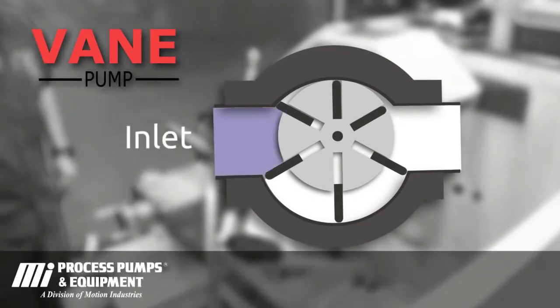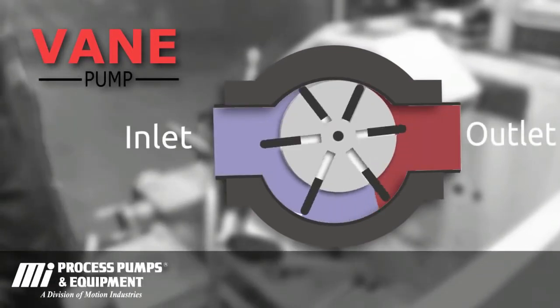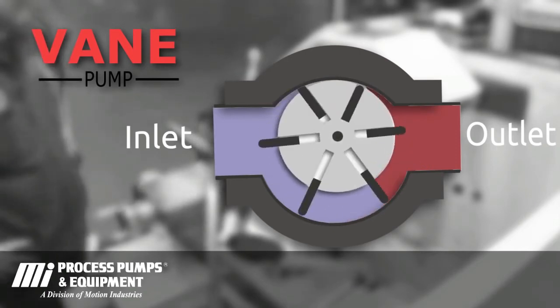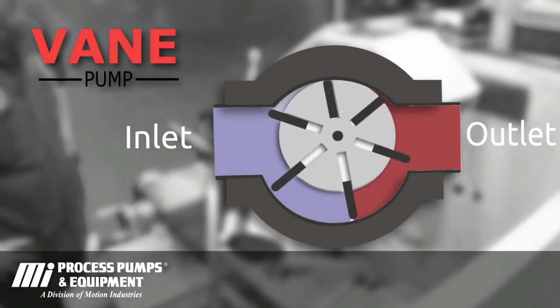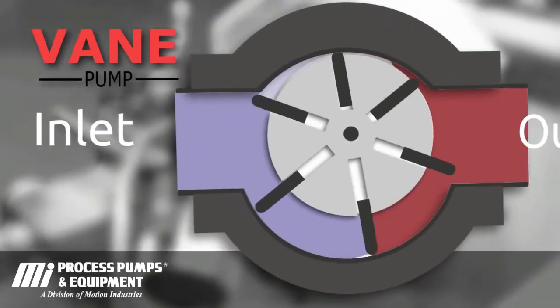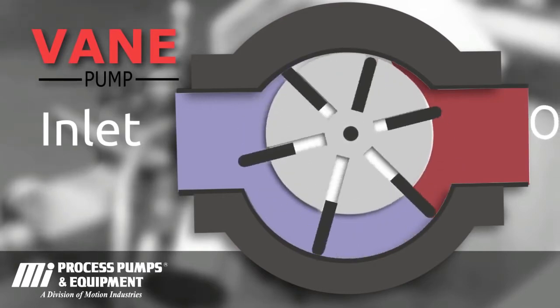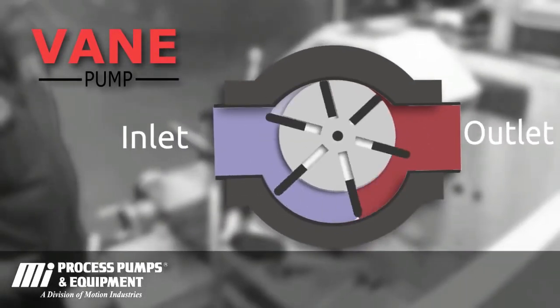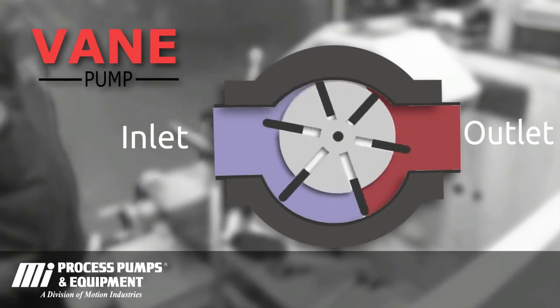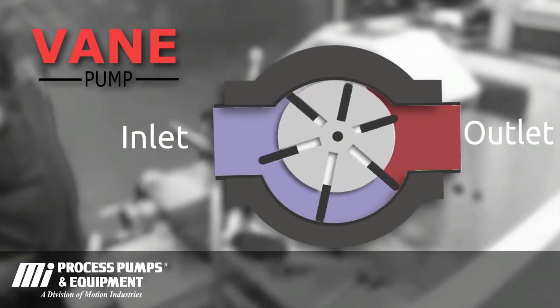Vane pumps are positive displacement pumps that have a rotor containing sliding vanes which slide in and out of the rotating rotor and seal against the eccentrically designed housing. This allows the vanes to expand the opening between the rotor and the housing on the inlet side of the pump to bring product into the pump. As the rotor continues to rotate, the vanes then slide back into the rotor, compressing the product out of the discharge port.